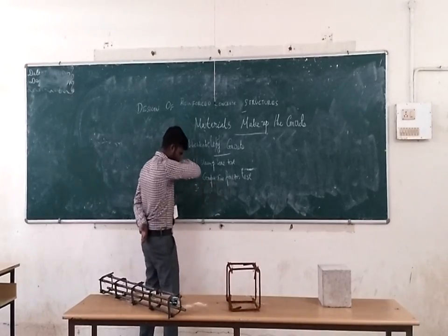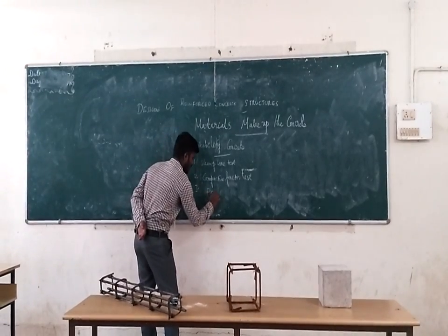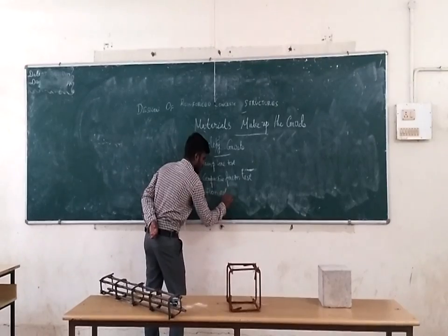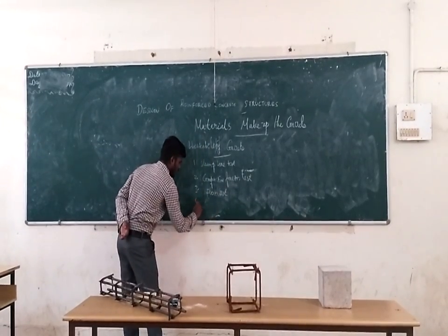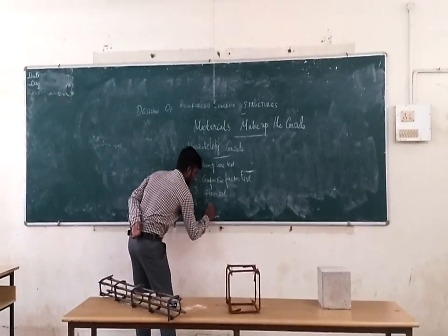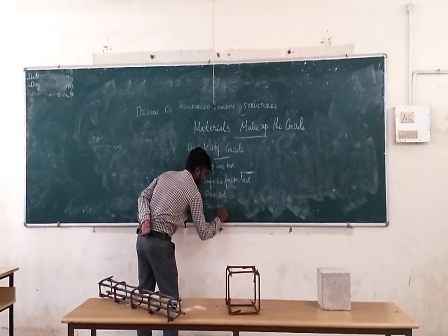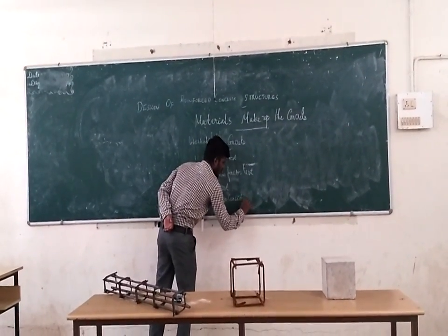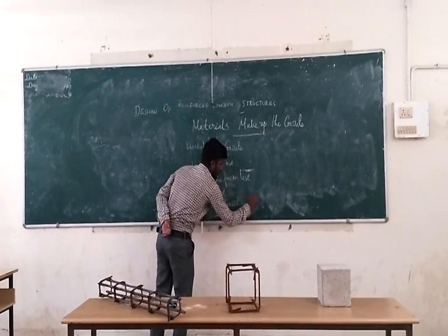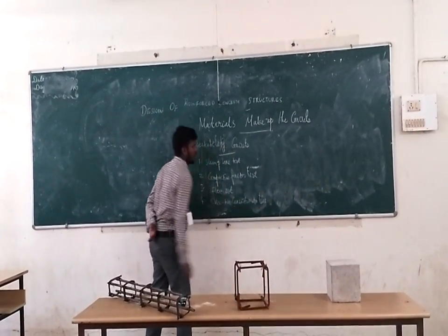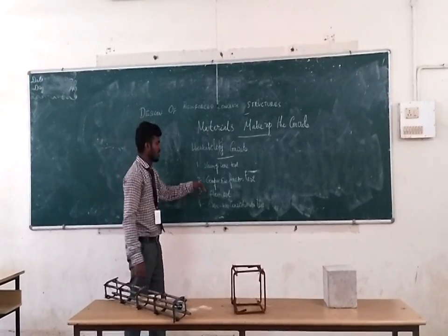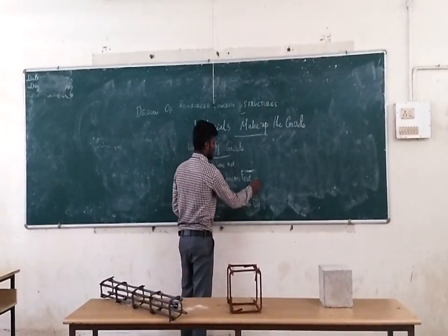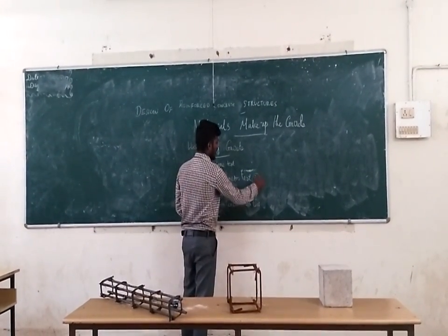Third one is the flow test. Fourth one is the Vee-Bee consistometer test. Out of these, the most accurate one is the compaction factor test.